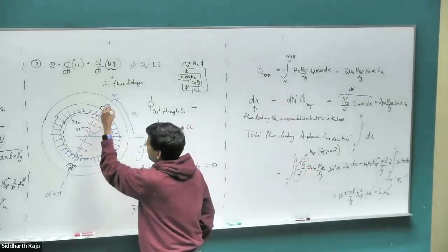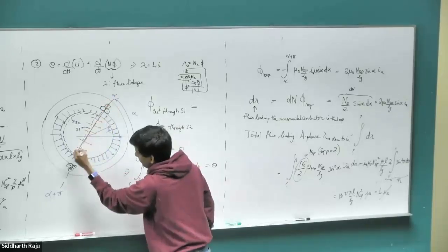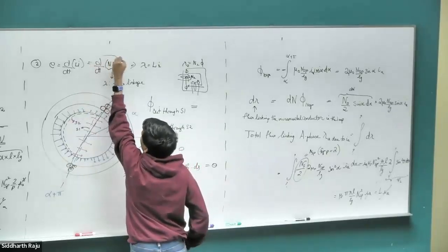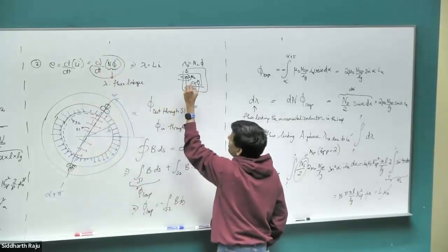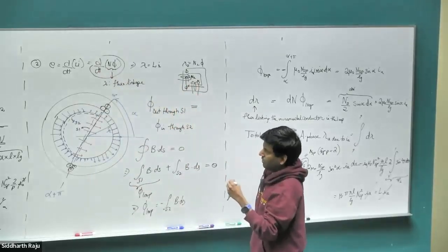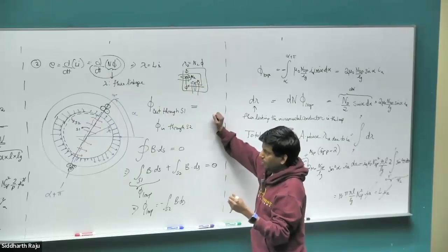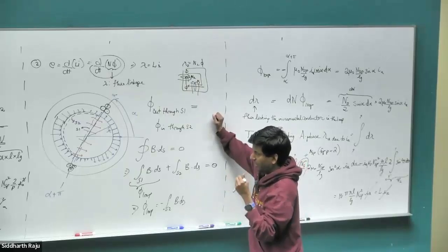The other problem is, if I take this loop, right, what does this formula say? N dφ/dt, that's basically the flux crossing through the loop that we are interested in. If you take the derivative of it, that will be equal to the EMF from our Faraday's law.